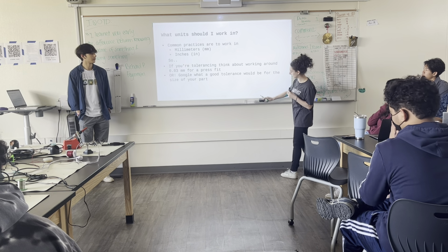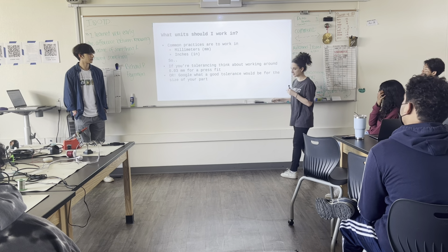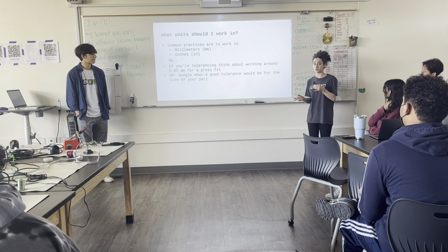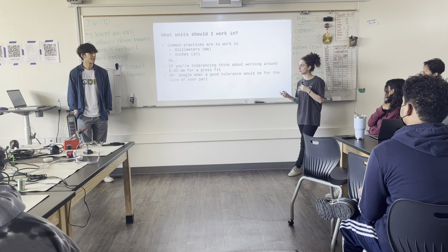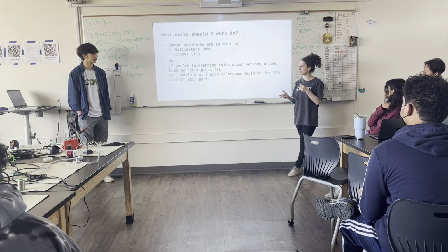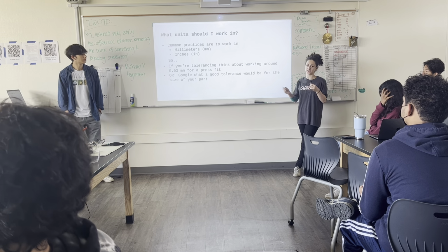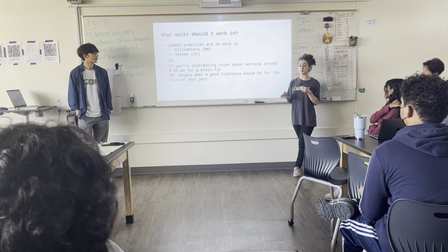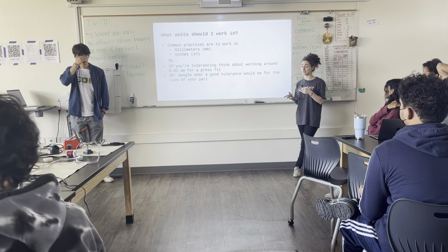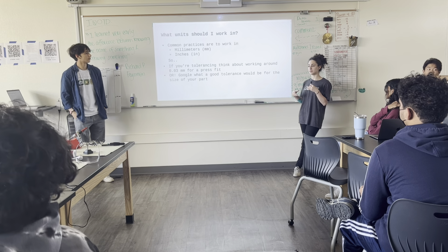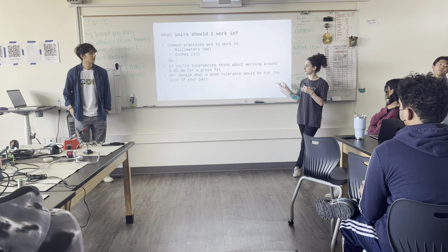So another important thing is just the general ways that people work in CAD is they use millimeters. I use millimeters. I think most of us do. Some people use inches, but it's not as common. So personally, I have a preference as to how I tolerance. Everyone has different preferences, but at the same time, depending on how big your piece is and what you're making, you can actually Google and get some advice on what your tolerance should be.